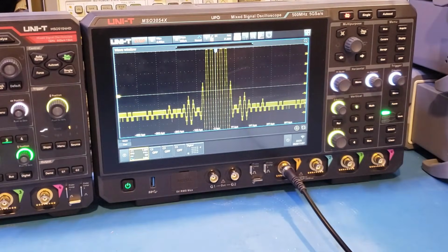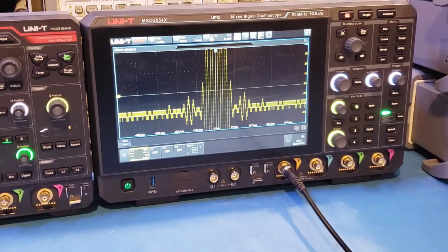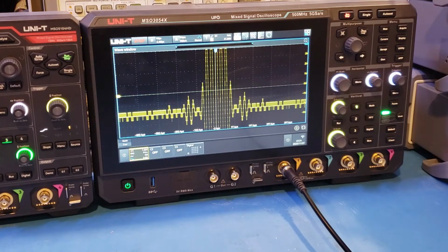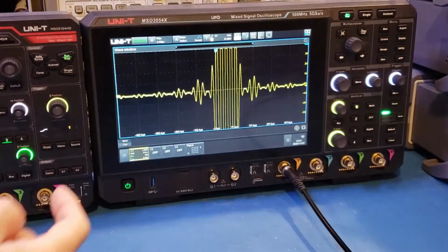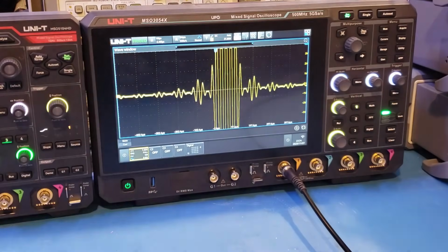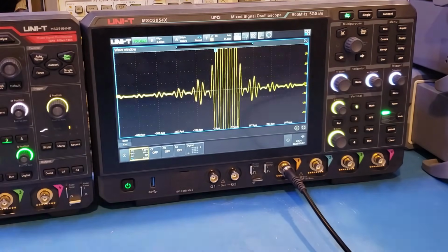So you can immediately see that the captured signal actually can see a lot of quantization errors. That's because we're capturing the signal using 8 bits. Of course, for repetitive signals, you could just recapture the signal again with the different vertical settings, so the captured signal magnitude can be higher, and therefore you will have more bits representing the signal, and the resolution will be naturally higher. For example, right now if I resume acquisition, you can see that at the same scale, of course, we can see with a lot more detail.